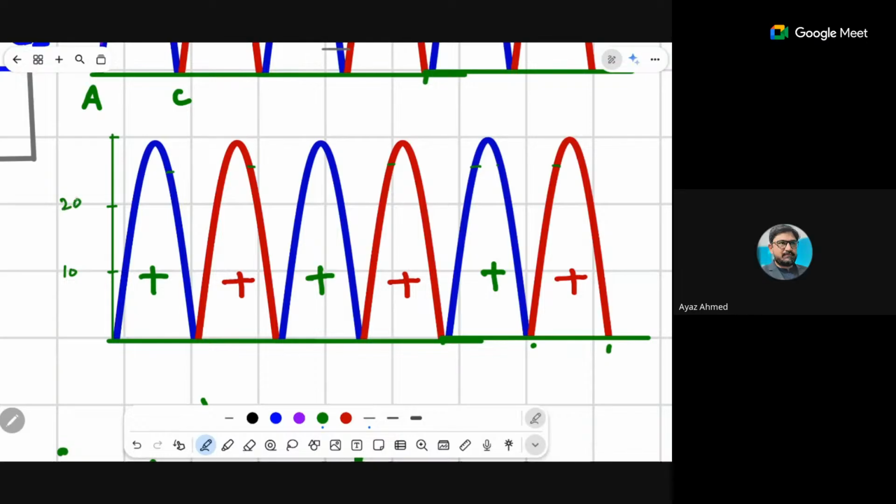Suppose 10, 20, 30 volts peak value, right? Okay, 30-volt peak value, and I want to make the voltage smooth to 28 volts. So you will just draw an invisible line at 28 volts, which can be again raised. This is the 28-volt potential difference. My voltages will be no more lower than that. Now what will I do? I will draw these lines for my charging and discharging.